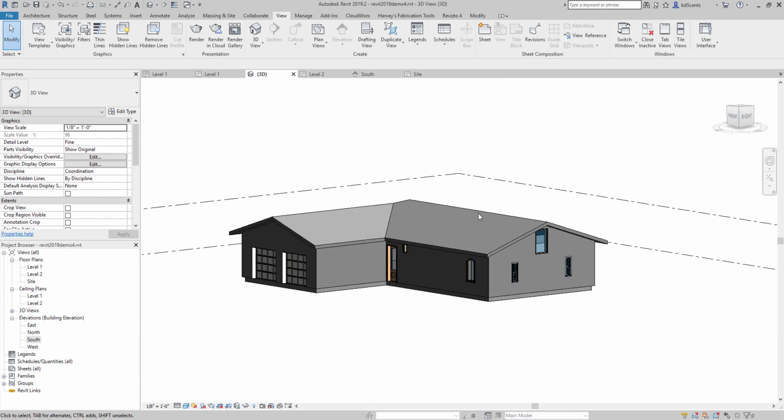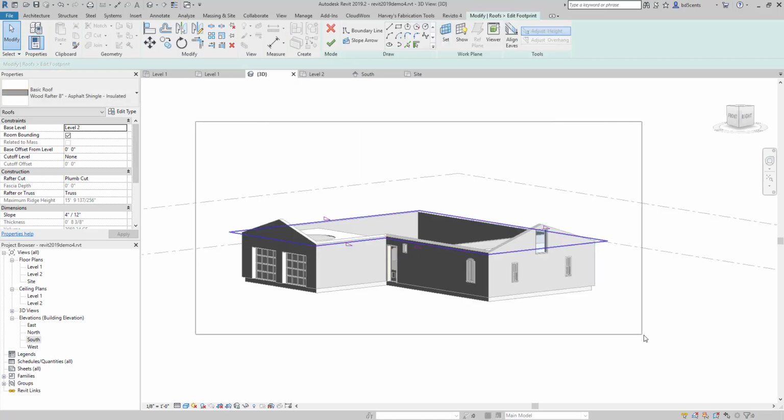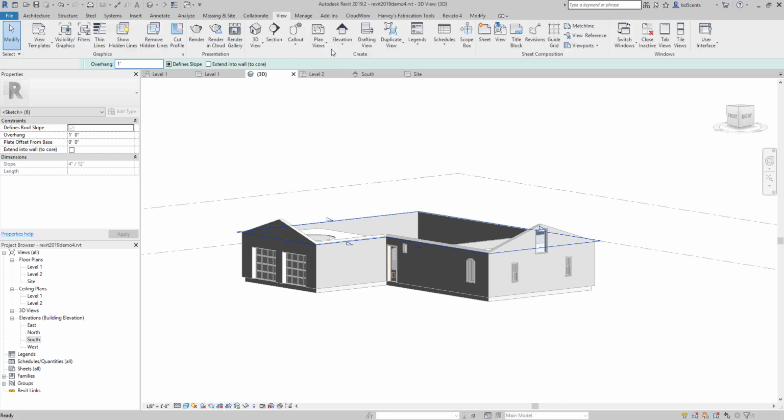We also want to adjust the overhang so that the overhang is set to 1 foot. So when I highlight these, I want to set 1 foot. You'll notice that the Define Slopes dialog box goes from a check mark to a solid black. That's just telling you that you have some areas that are sloped and some that are not. You could uncheck this and then check it, and it'll define it, or uncheck all. Go ahead and play around with that, but for this section of this exercise, I'm just going to continue by hitting the green check mark.